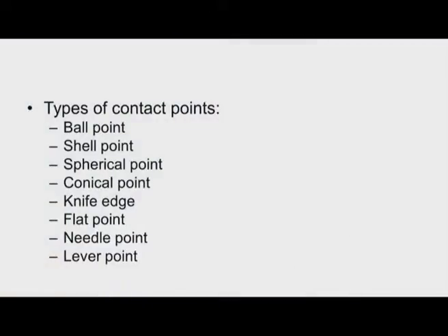Now, there are different types of contact points. Plunger ends are available like ball point end, shell point, spherical point, conical point, knife edge. So, depending upon the application, we have to select the proper contact point. For example, say we have a very narrow groove like this. In such cases, we may have to go for a knife edge type, so that it will enter into the groove comfortably.